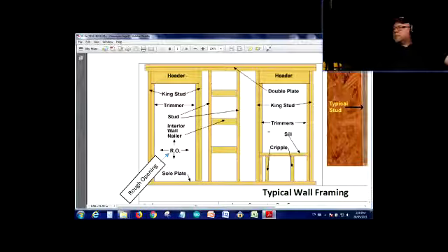On top we have wooden plates called headers, from the head type of thing. Then we have the studs that go from top to bottom, and something called trimmers. The layers keep adding on. You have the sole plate, and the double plate or head plate on top. You also have cripples, which are miniature studs just to keep the structure intact.